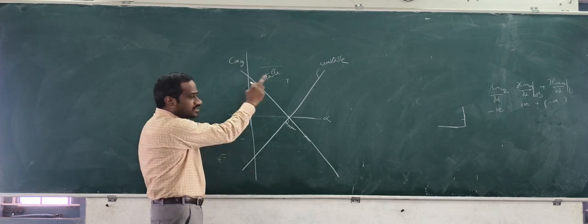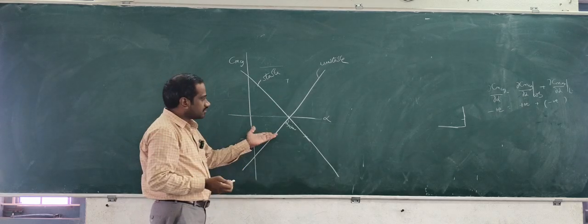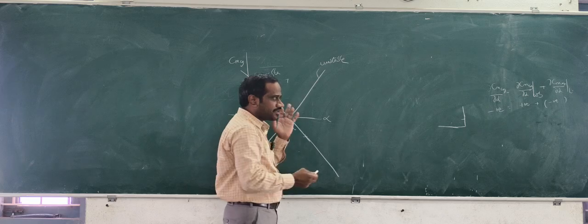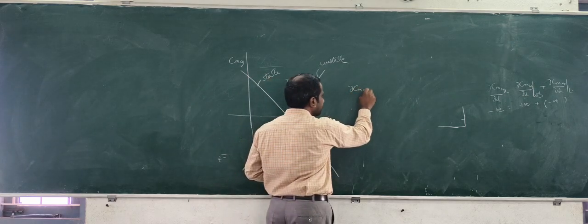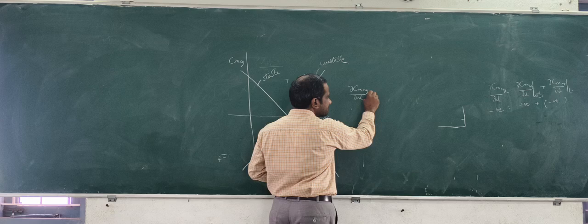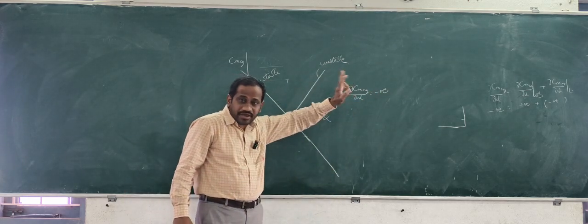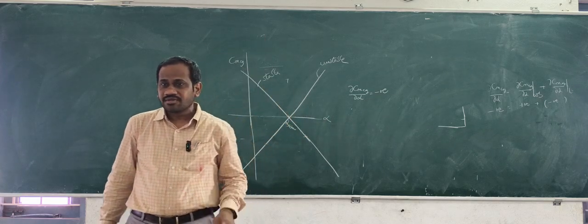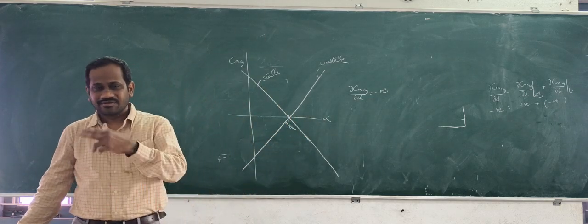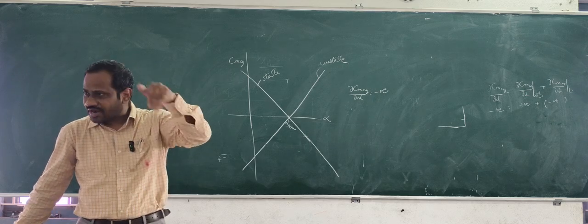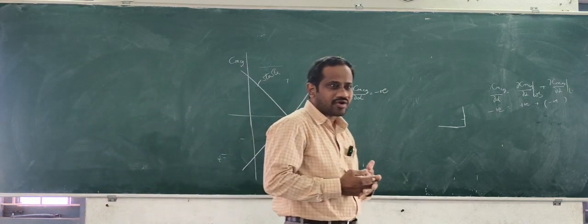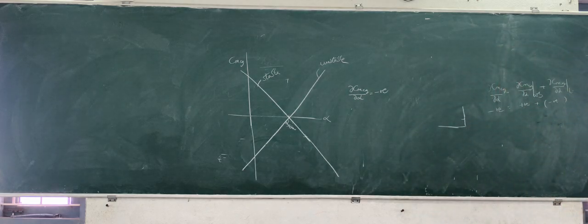We are going to represent the whole discussion in mathematical format. So, to have longitudinal static stability, dou CMCG by dou alpha should be negative. That's what you understand. It being negative means the contribution of the wing and tail should make this equation negative. Now look at dou CMCG by dou alpha we had in the previous discussion: CMCGW plus CMCGT, there will be an equation. Differentiate with respect to alpha of the aircraft, then that value should become negative.